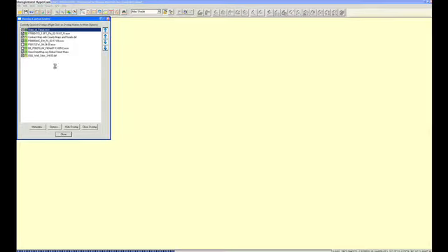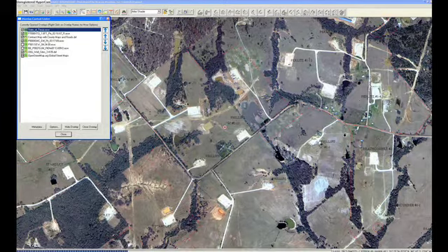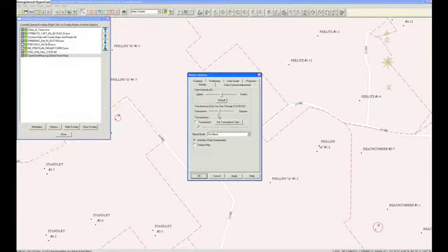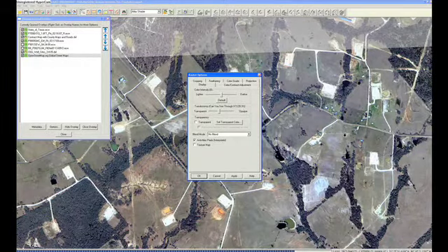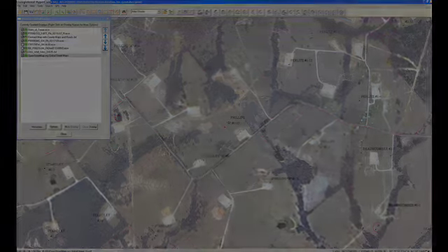And now then, for additional orientation, we can just do a file, basically a file open. It's actually fetching from the internet street atlas information. And so we'll add that as a layer. And with it, we'll be able to see what roads are within this location. Now back to our control center, we've got the ability to control what's on top, what's not, and intensity. Here we'll change the transparency so that we can still identify our roads and also see the imagery at the same time, actually along with well site information.